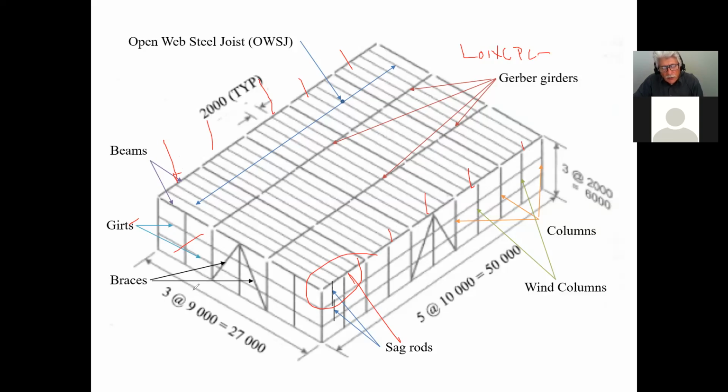But on the short side, you have to be careful because you have this one here, okay? On the short side, you have to be careful when you design the column, because you take this one for the design of the beam, but then when it comes to the columns, you have to decide whether the load from your girder is much higher than the load from the column, and we'll worry about that when we get to columns. So don't worry about that. And that's when we're going to be worrying about designing the exterior columns.